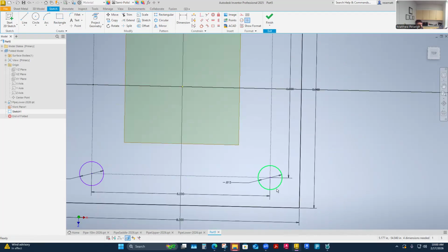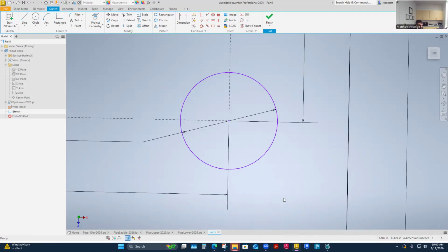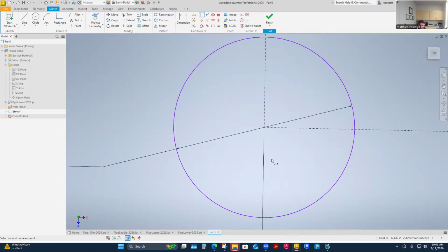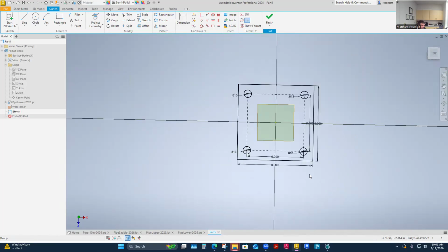And so patterning it wouldn't have had this kind of an issue, but I like to show maybe different. It seems like you can't move it. You try to flex it and it can't flex. But I'm just looking to say, I just want to constrain these two together. So I'm just doing a coincident constraint from the center to the center. And that's all that's holding that in.